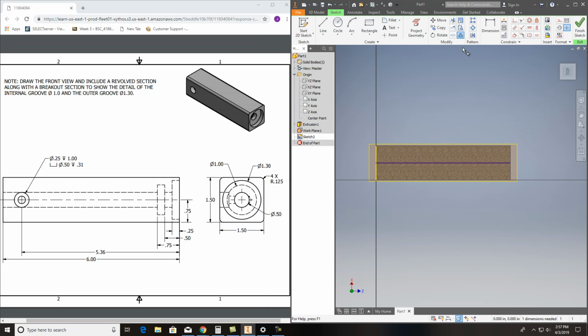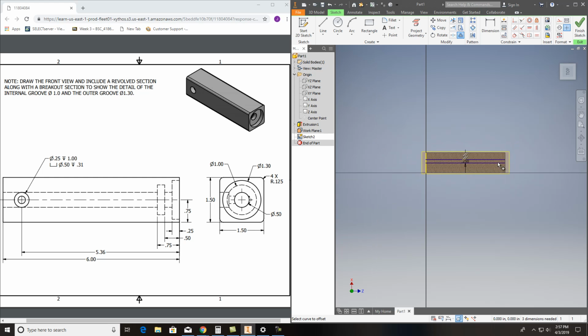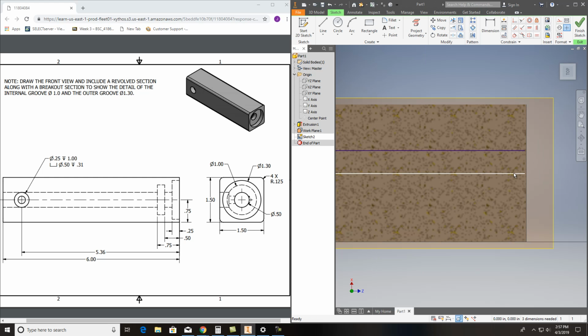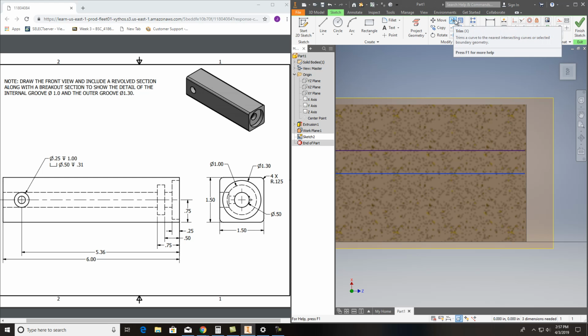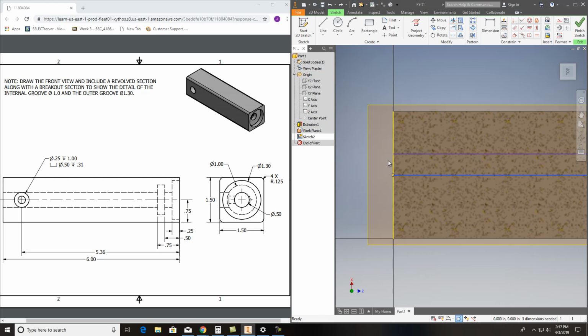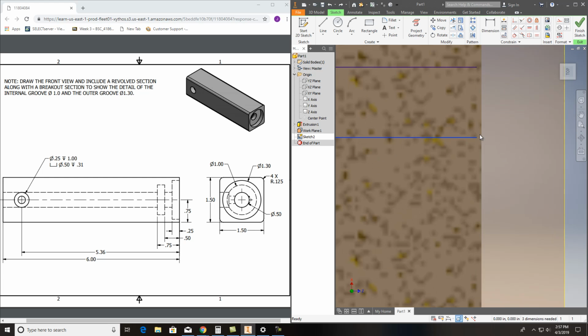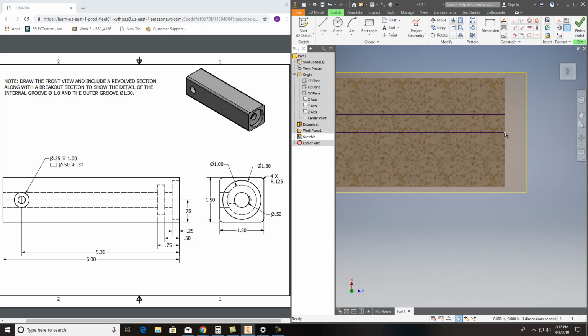And what I want to do is hit an offset here, come up 1/2 of an inch, because when you're revolving something, you're taking 1/2 of it. And then that goes all the way through, and I'll zoom in and make sure these go all the way to the very end. So I want to hit Extend. Trim, extend, and that's okay. We'll extend them a little bit. We'll extend that one on out. We'll extend that one on out. And that's our 1/2 of an inch.